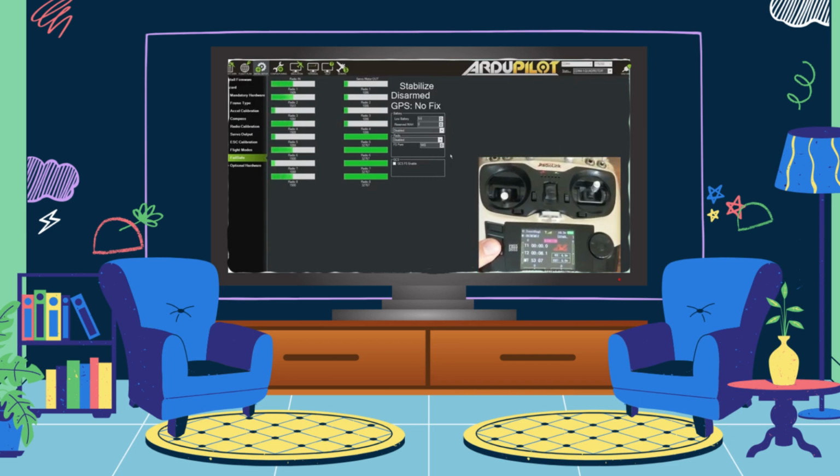And that's it. Now let's see if our settings are working properly. First, I set it to any value while the remote is on. Then, turn off the remote. After turning off the remote, you will see that channel number 3 drops to a value of 941. So, we activated failsafe. Now let's turn the controller back on. After the connection is established, we see that channel number 3 starts working normally. It sends a minimum of 1091. When we turn it off at the minimum, it drops back to 900 values.